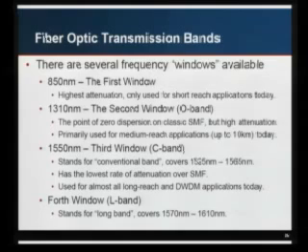The second window is the 1310 window. The reason this is important is it's the point of zero dispersion for classic SMF, the fiber that people originally deployed back in the 80s, early 90s. It has higher attenuation than, not higher than 850, but it's not the lowest point of attenuation, but it's the lowest point of dispersion. And today people use it for medium reach applications, and it's called the O band. O stands for original, for whatever that means.